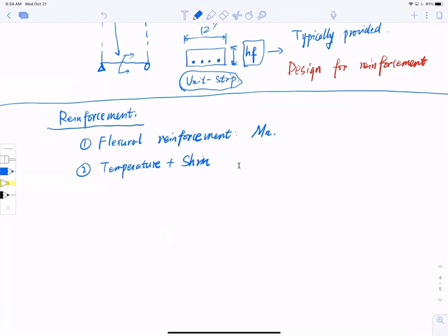Hey, Bob. I have a question. Go ahead. How do you account for shear resistance in these slabs? Stirrups don't make sense to me because it's so wide. That's a good question. You see, hf is normally very stocky, it's very short, and the slab usually does not take a whole lot of shear. So we don't usually provide any shear reinforcement in the slab. In structural design, we try to allocate the shear to the beams underneath it.